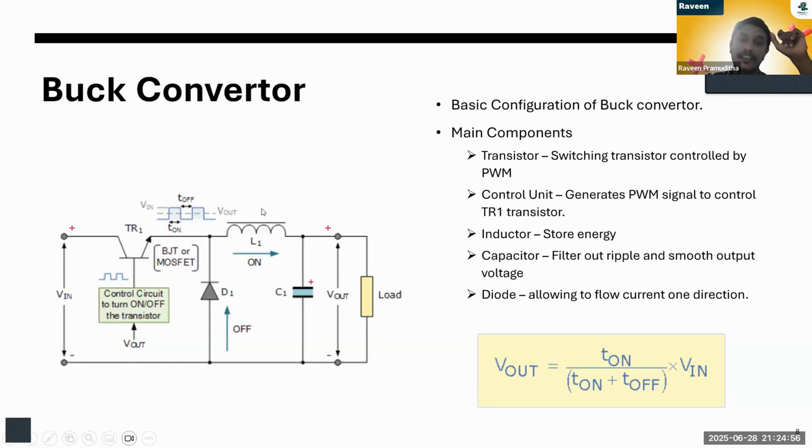So then it will work as a voltage source again. The current goes through the load and this circuit, completing the loop through the diode. So the current through the load is constant. Okay, so then we can provide constant voltage using this kind of circuit. We mainly control the duty cycle of the PWM signal.